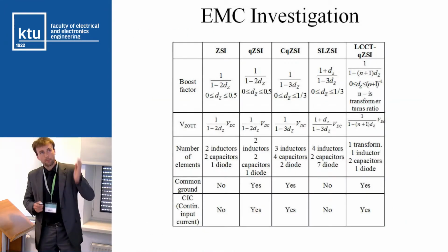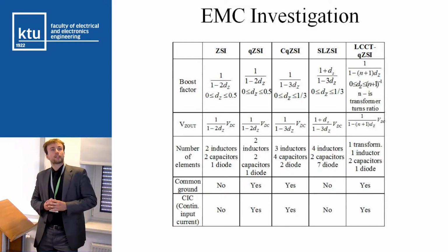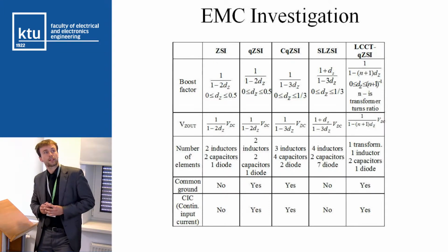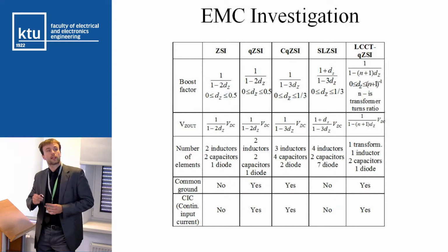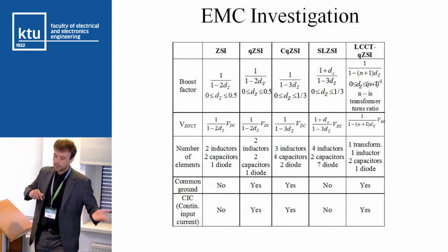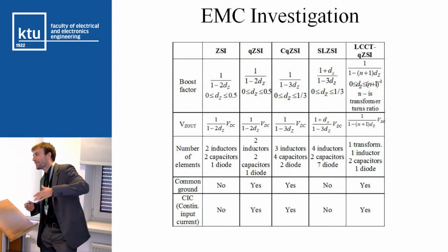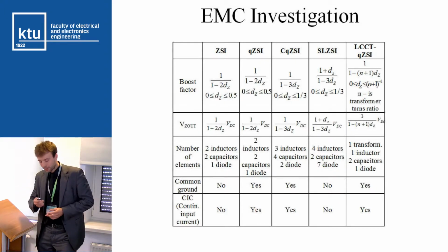Okay, every structure has other parameters. The most important are boost factor, number of elements, common ground, and whether the structure has a continuous or discontinuous input current.